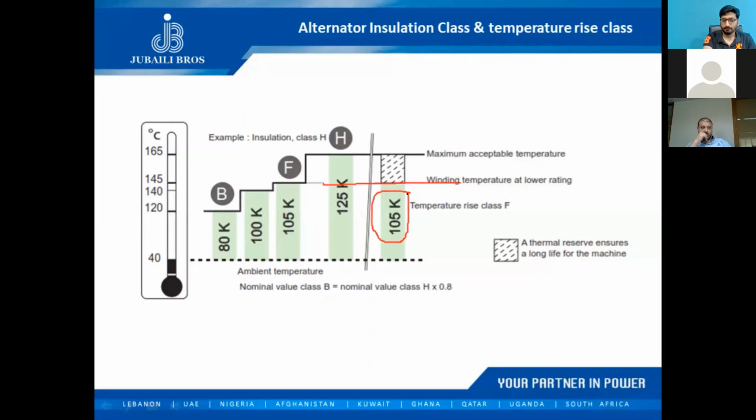Okay, temperature rise class of F. You see there's a margin between the insulation class and the temperature rise class. This margin here, this reserve, is called temperature rise class. So this ensures a longer life for my alternator.